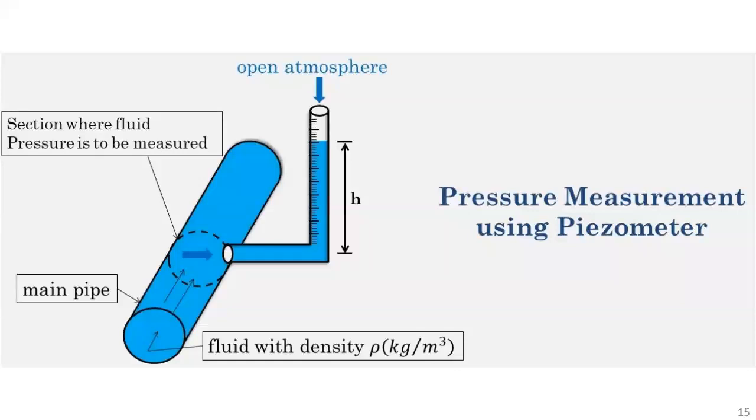And again, the manometer could be off to the side. So here we have fluid flowing in the pipe, but there's no flow in the manometer. It's giving you a static reading. This manometer is no different than if you just had a pressure gauge on the side of the pipe. So in the Bernoulli equation, or the energy equation, that P over gamma term, a manometer could be giving you the pressure, or just a pressure gauge could be giving you that pressure.